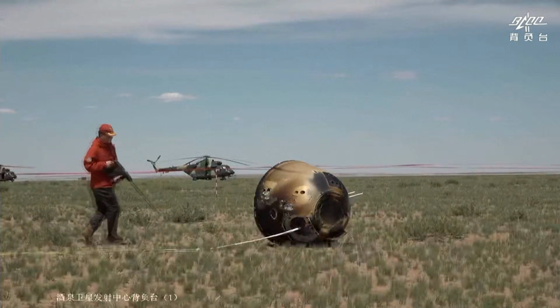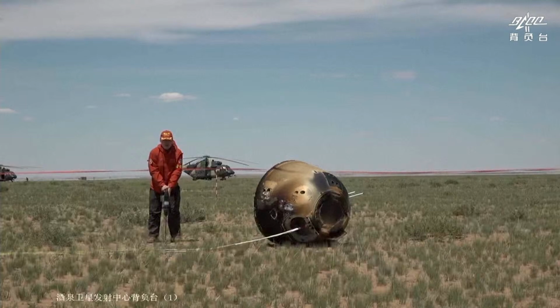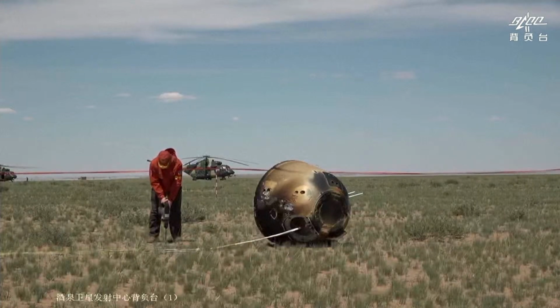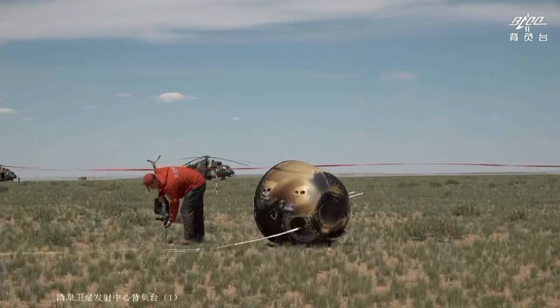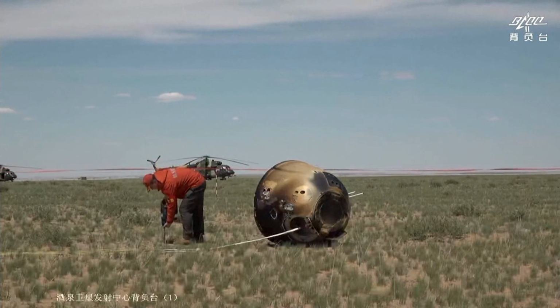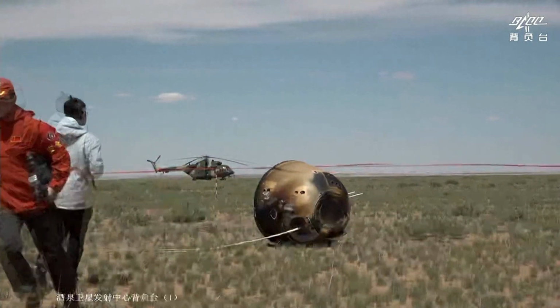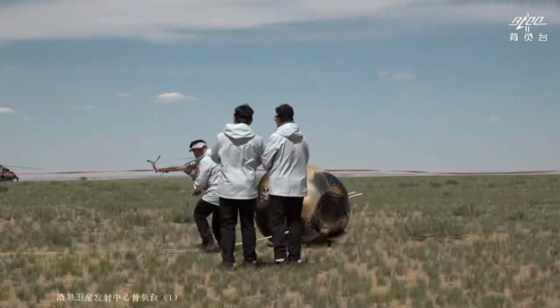I always mention to the media that our Chang'e 5 and Chang'e 6 missions are like unmanned, miniaturized Apollo missions, because the whole mission profile is almost the same, with the rendezvous and the docking in the circumlunar orbit. This is the most complicated mission design, but has the highest efficiency. That is the reason why we can get about 2 kilograms of samples with such a small vehicle.